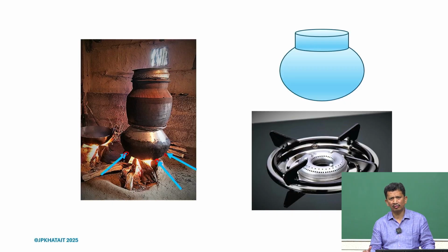The moment we have four supports, we have issues. In this case we have some rubber mountings and we see a lot of chatter. Sometimes they make contact here, and if there are some tolerance issues, we will have a problem and we can see some chattering, some noise.